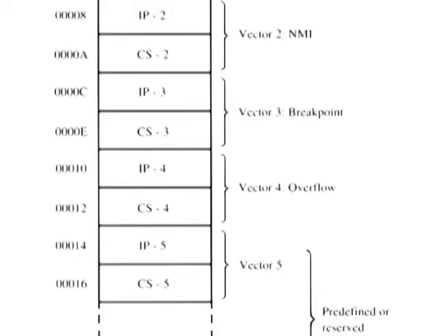The interrupt generated after every instruction will transfer the program control to a location corresponding to the address pointer 1. The routine corresponding to pointer 1 is required to facilitate step by step operation of the CPU and allow the user to see the contents of the various registers for better debugging in step by step mode execution. The pointer 3 corresponds to the breakpoint and pointer 4 is used for overflow interrupt.